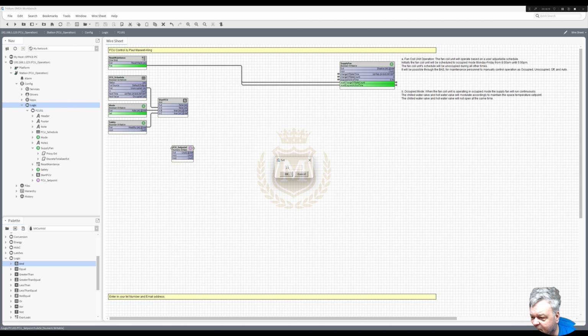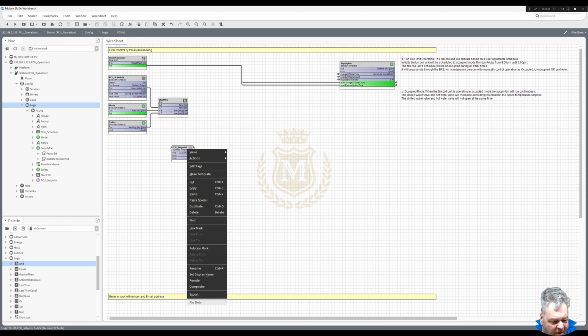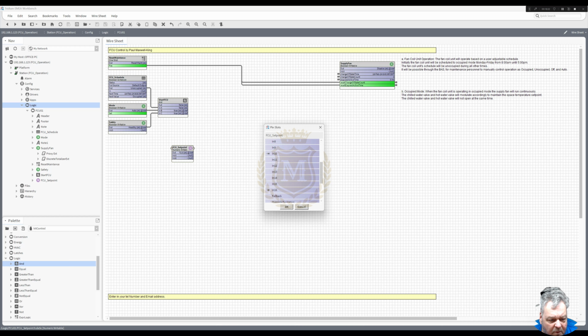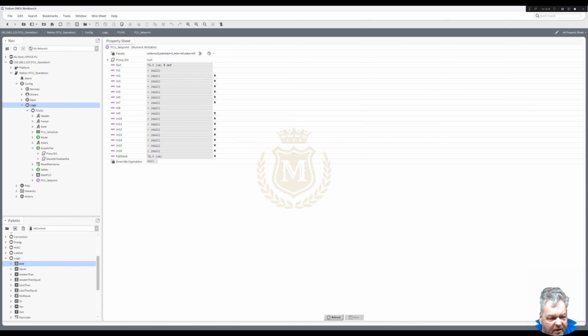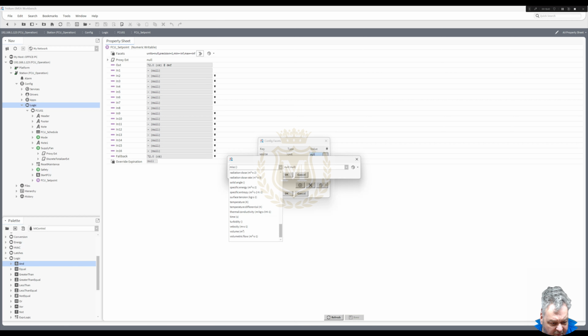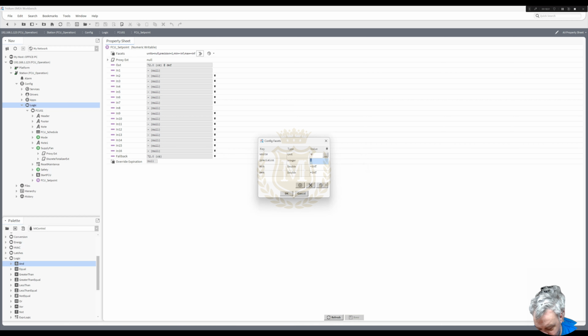Oh, we're in Fahrenheit, aren't we, on this job? Occupied space set point is 72 Fahrenheit. Normally don't work in Fahrenheit, but let's see how we go. So we don't need any of them, and we've got the set point in there. We better change that to Fahrenheit. So we'll go to temperature and Fahrenheit. Okay, and we won't have any decimal places after it.